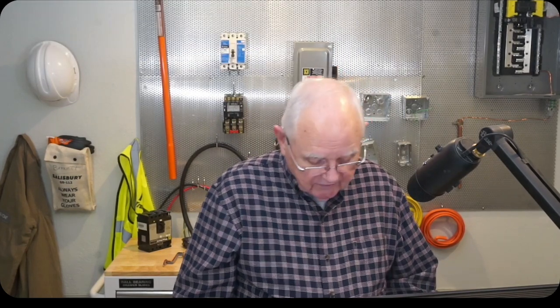The flywheel storage system shall be provided with a containment means to contain moving parts that could break from the system upon catastrophic failure. Probably a good idea. The spin down time of the flywheel energy storage system shall be provided in the maintenance documentation. Righty? So anyway, and that's it on Article 706. Now keep in mind there are plenty of other articles that tie in anytime we're going to install or maintain an energy storage system. Take a look at NFPA 855. That's an excellent document on the installation of these energy storage systems.